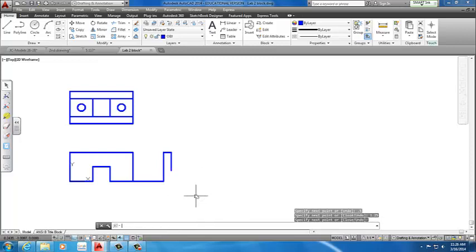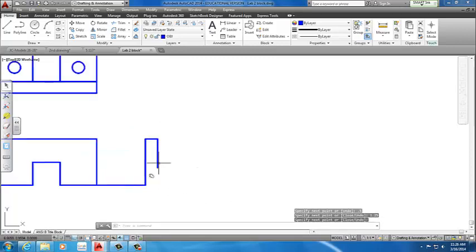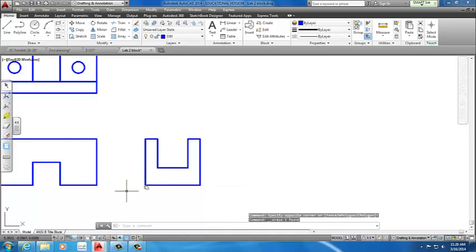I can stop there and then start from the bottom now. The bottom dimension all the way across is 2.24. I'm going to change my dimension style because it's showing these marks a little bit too big. Again, across 0.5, and down 1.25. You guys don't have to do this. I'm just doing it for myself. Now all I have to do is snap onto this endpoint here and close my object, giving me the exact shape I'm looking for. I need to change the marking size.